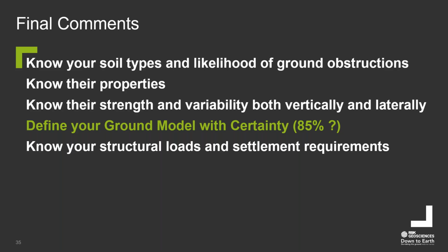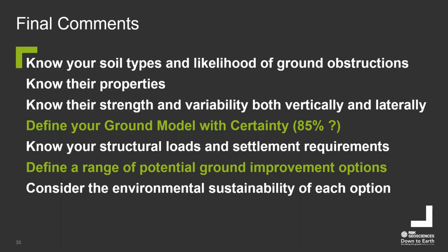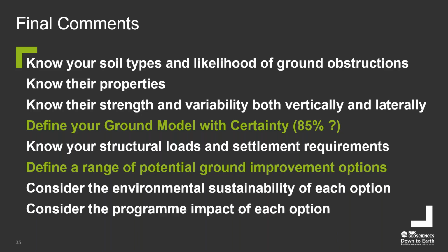Understanding the loads at the very beginning, so knowing what is required on the site, is just crucial really to then design the investigation appropriately and to make sure the right ground improvement techniques are put forward, particularly settlement requirements, not just the loading, but how it is going to move. So this is really then allowing us to define the range of ground improvement options. We can then look at sustainability, etc.